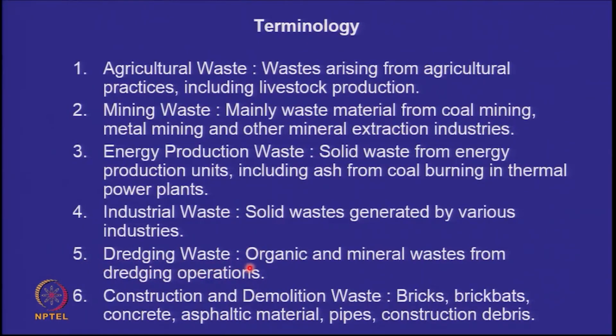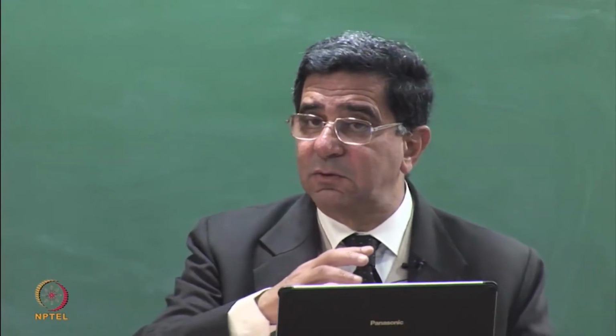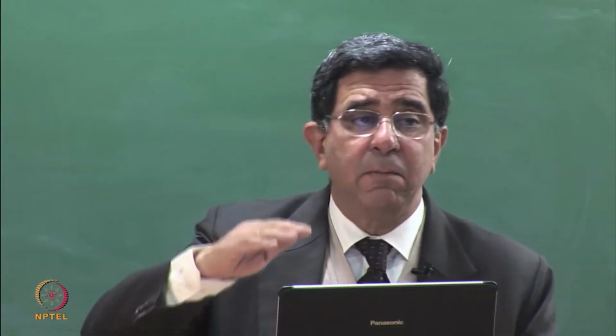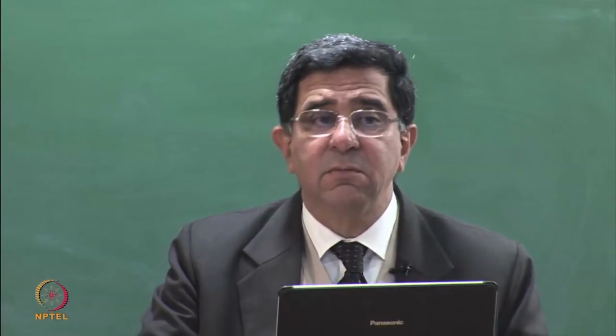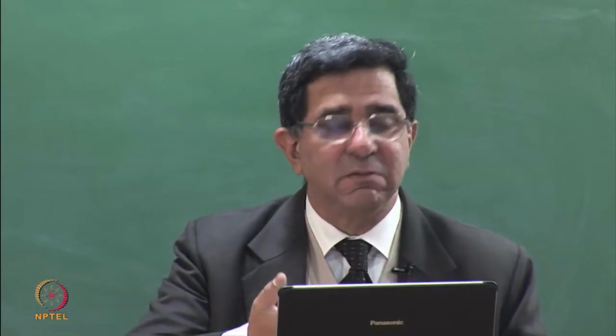Dredging waste. So if you look at the Najafgarh drain, as liquid waste flows in a drain, the heavier particles tend to settle down at the bottom. So from time to time, we have to clean up the channel so that its carrying capacity is not reduced. So often you will see a drag line or a backhoe cleaning up a drain, and this black sediment at the bottom is lifted up and placed on the side.